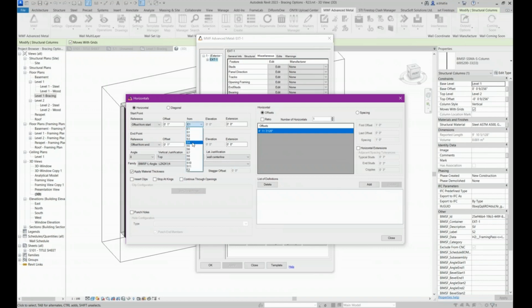If you wanted it to go like say from S4 to S7, you could do that as well. And you'll notice that the offset automatically adjusts on its own. So if you need to add it for cabinets or something and you know exactly which studs the cabinets start and end on, you can choose those options for the stud number here.